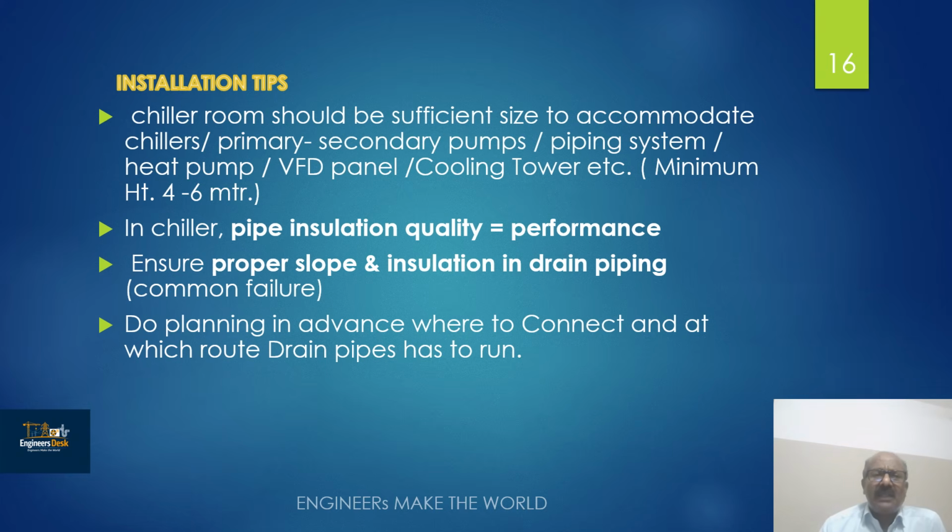As a part of installation, what are the major tips and points to be taken care of? The chiller room should have sufficient space and location to accommodate the chiller, primary and secondary pumps, VFD panel, heat pump, etc. The cooling tower is generally kept outside the building or on an open terrace. VFD means variable frequency drive. Instead of starter panels, nowadays VFD panels are used for smooth starting and stopping of chillers.